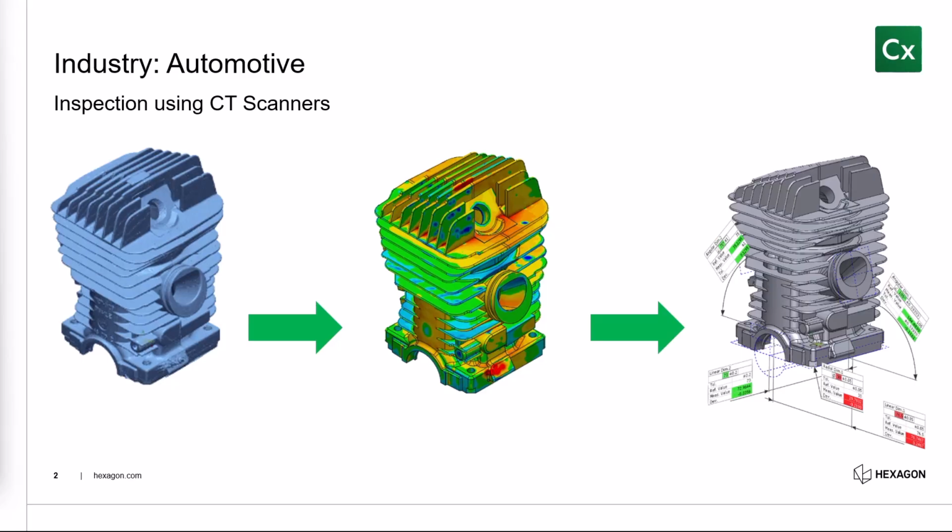However, you can use CT scanners as well. It all depends on the material. If it's very, very dense and hard to penetrate through, you may have to look at some higher frequency or change the resolution size and so forth. But the benefit of CT scanning over something like handheld or ARM-based systems is it can reach areas that the other systems that I previously mentioned cannot.